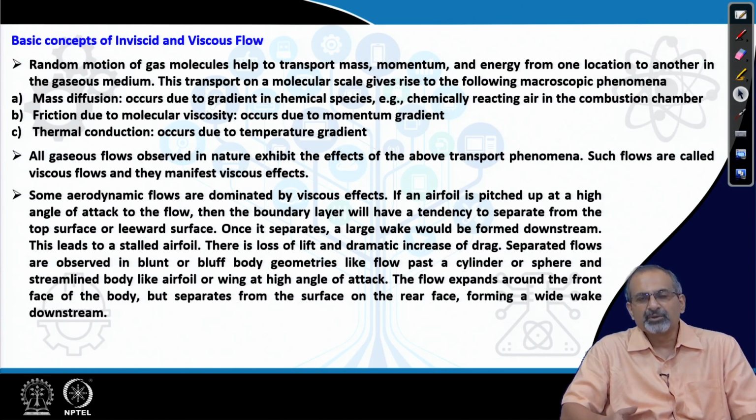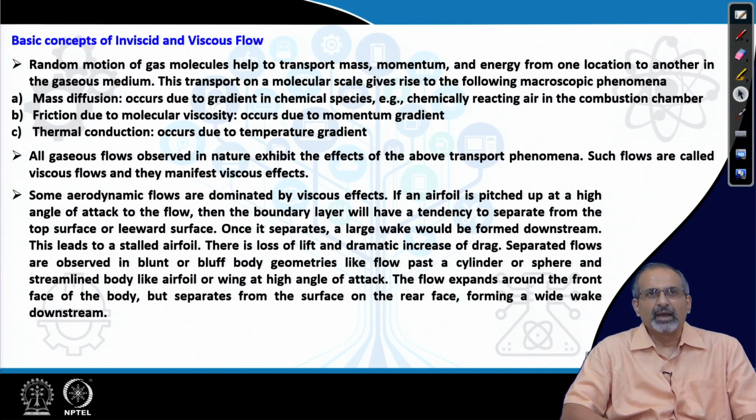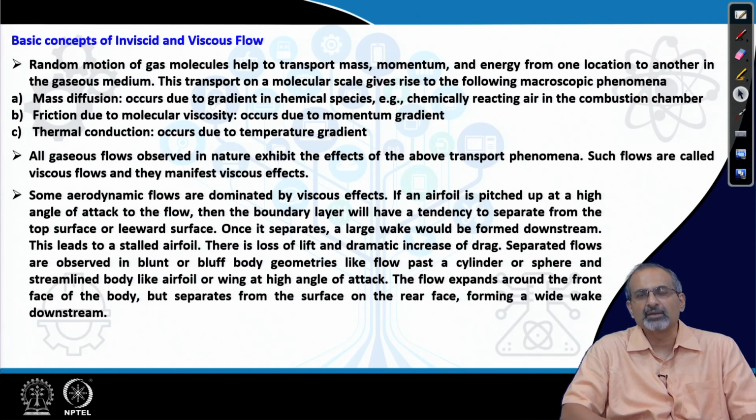Once the flow separates and leaves the surface, a large wake is formed behind it, and because of the wake formation downstream of the body, we find there is a dramatic increase in drag and reduction in the lift of the body. This reduces its aerodynamic efficiency. We call this a stalled airfoil.